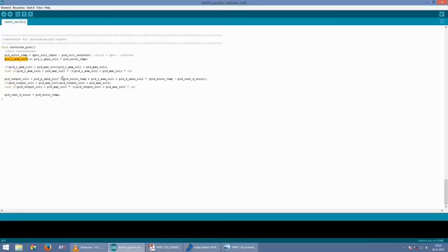To prevent the I controller from going out of control, we need to limit the output to the same output limit as set at the top of the program. After this, the complete PID output is calculated. The P gain is multiplied with the error and the D gain is multiplied with the difference between the current error and the previous error. Again, the controller is limited with these two lines because the P or D controller may cause some extreme outputs. And last but not least, the current error is saved for the next calculation.